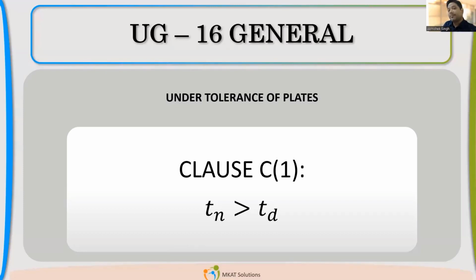If I'm giving an order to a plate manufacturer for a 10 thick plate, he cannot exactly make 10. There is no absolute value in terms of manufacturing. You always need a tolerance. Yes, Tejasvi is also right. You always need a tolerance, positive and negative: what is minimum, what is maximum.